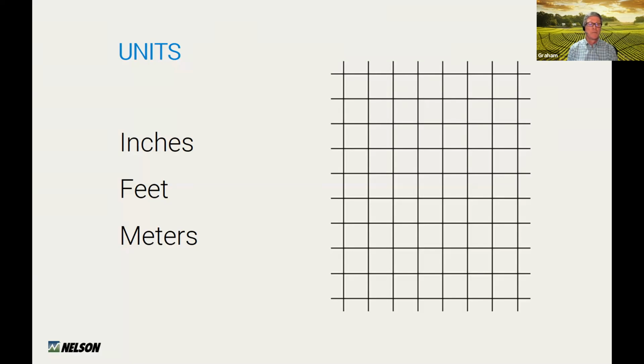I knew it came from the metric world, so I had IRRICAD in meters. But because it had gone through AutoCAD with default units set to inches, the scale was off by a large factor. And often there's no breadcrumb trail of units when files are migrated through various software. So it's something to check when you import things to make sure things are to scale.